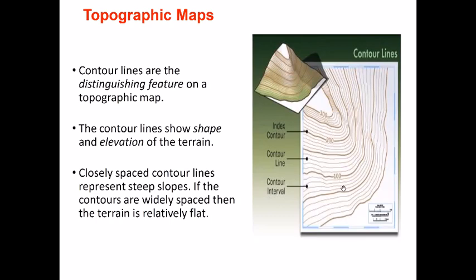That means what is the difference in elevation between two specific contours. And this elevation can be anything. It depends on what sort of project you are doing, how much should be the difference between the elevations, or what is the nature of the land. It depends on a lot of things. Basically, if I try to make contour lines for smaller contour intervals, the work that I have to do in the field will increase a lot. So that is why a lot of factors are kept in mind before deciding on the contour interval.